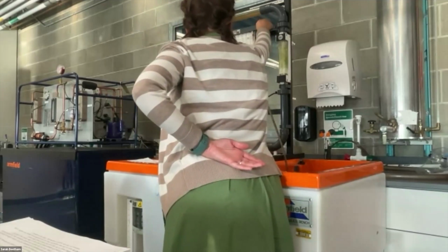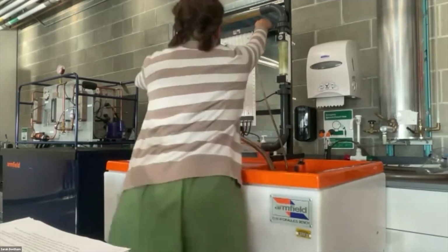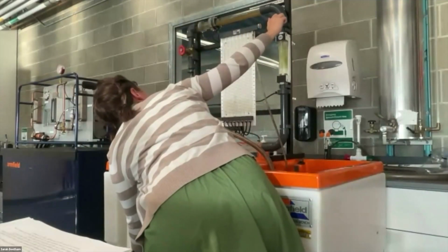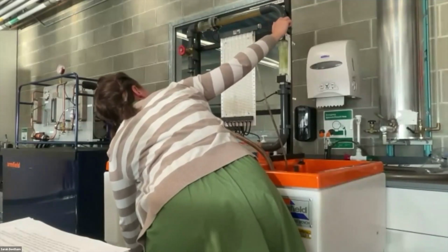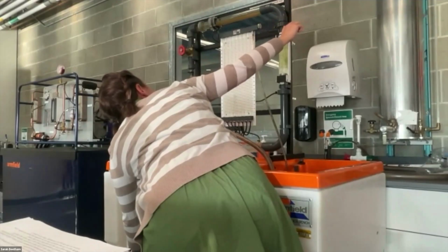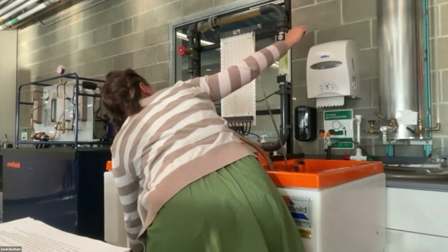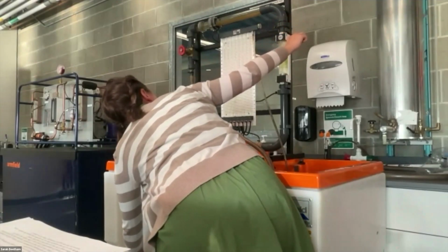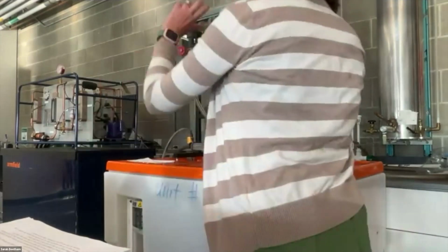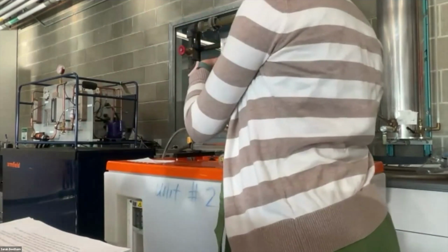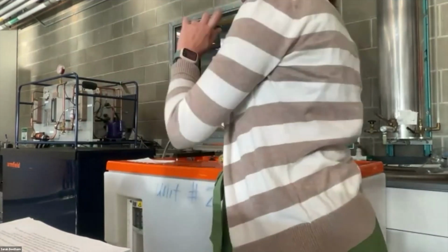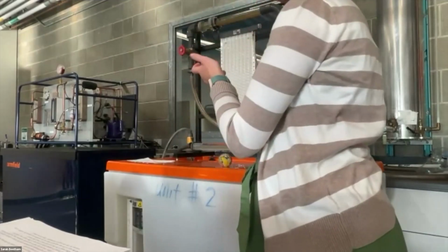So when I open this, it's going up a little bit. And then, so I put a little bit of flow through here. And you can see it starting to move. And it's probably hard to appreciate, but very small adjustments to the control valves will cause this to change very quickly. So the name of the game really is to move quite slow with how you're adjusting these.